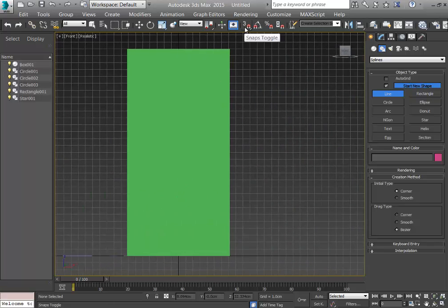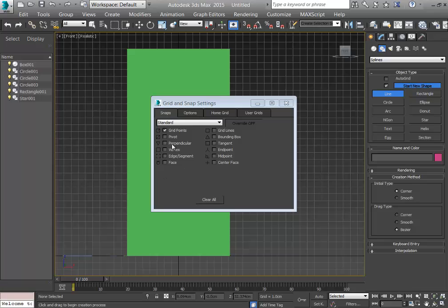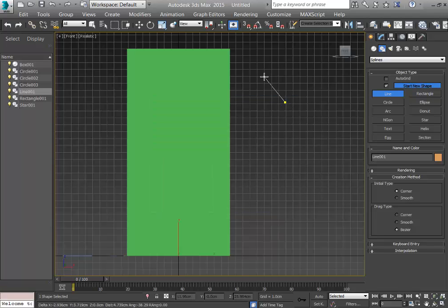Okay, so I'm just going to see from the front view, and I just zoom in again. Once I click the snapping tool with a right click, here I have some options, and the grid points should be active. So the mouse should snap to those corner points of the grid. If I just say OK, and if I move my mouse, see there is a crosshair coming, and it's always passing through the corners.